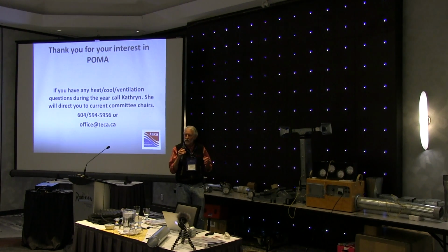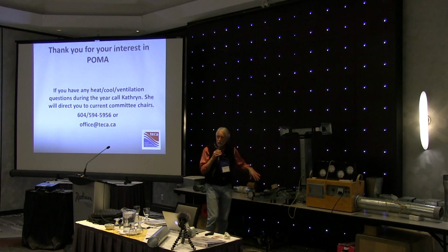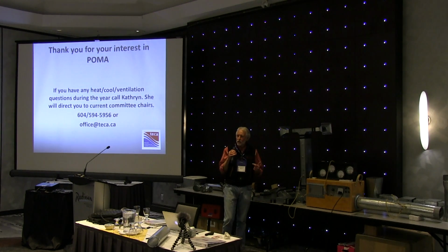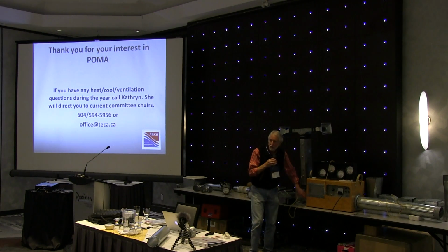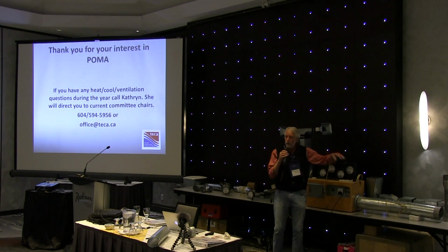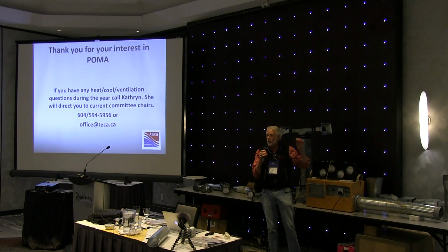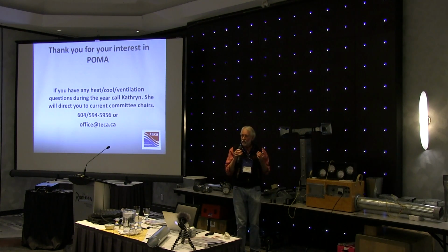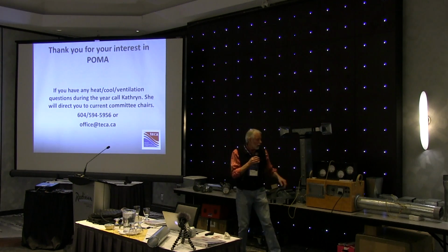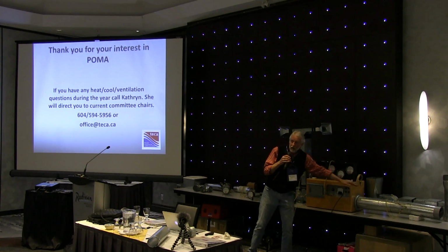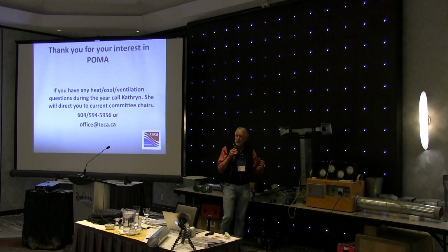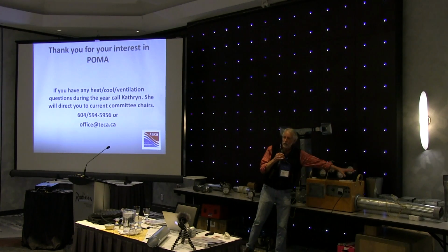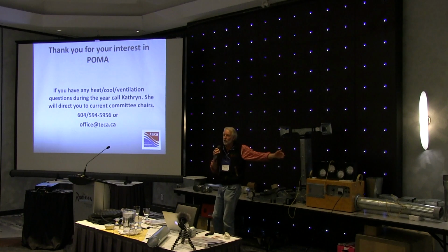So when we teach it, the most economic answer was to split that pull and push to be equal. But if I was doing a house right now for myself, I'd make the pull real easy to give me all sorts of pressure available for a filter, and have lots of push so that I get into the far corners of my house. Because that's what Mrs. Smith is always upset about. We can't get enough air to her back bedroom. And that problem is created by two things: too small and too many changes of direction on the supply, but it's equally caused by an overly restrictive return, because all of the capability of the fan is used here when it should have been used where we have less difficulty.